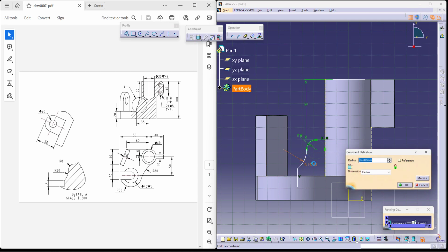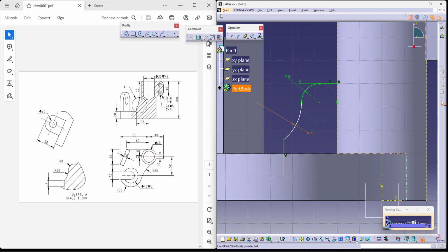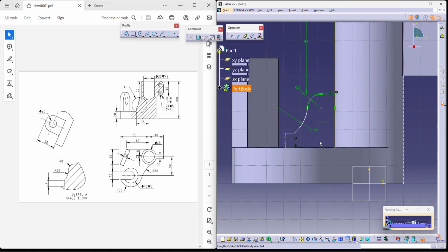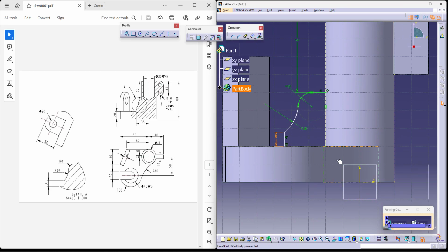I will coincide that a little later on the body. This has to be in coincident with this face. Now we know that this distance is 8. These are your actual dimensions. Now from the center, he has given a dimension of 35. That is from this center, which again I have taken 0, 0 in the beginning. So I can easily constrain the body using these.